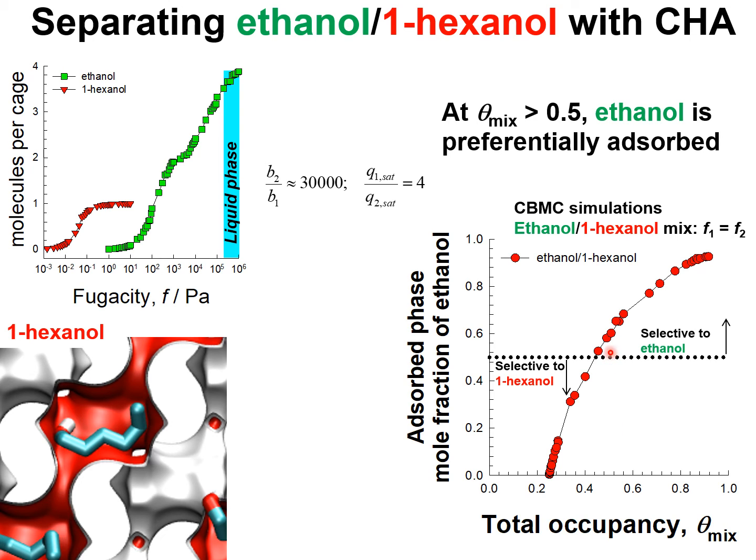At pore occupancies higher than about 0.5, the selectivity reverses in favor of ethanol, and at occupancies approaching unity, the adsorbed phase mole fraction is almost pure ethanol.